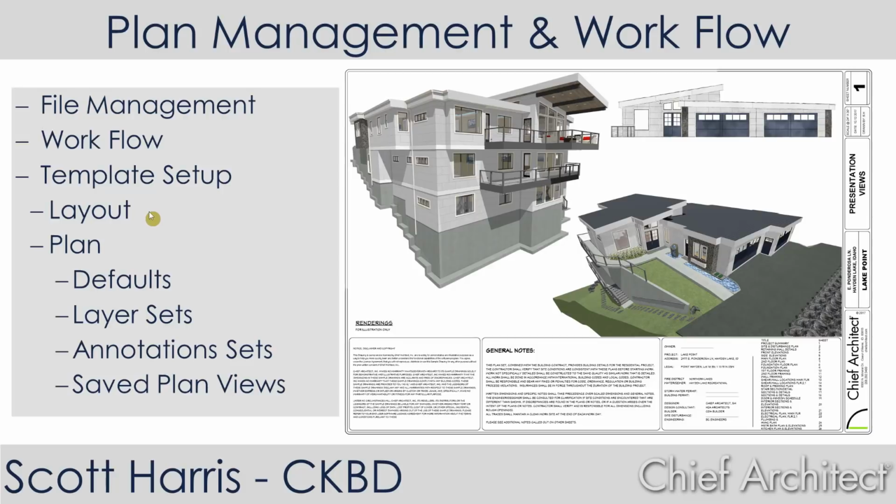The next component is creating a template for your plans, similar to a layout, but there are different components you want to set up. I'm going to go through and talk about defaults for floor platforms, other components, layer sets, annotation sets, and a new feature beginning in X10 called Saved Plan Views.